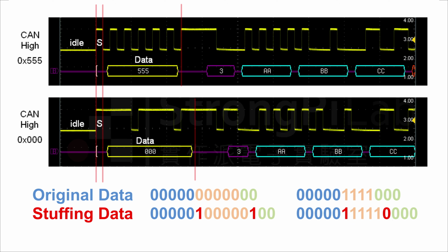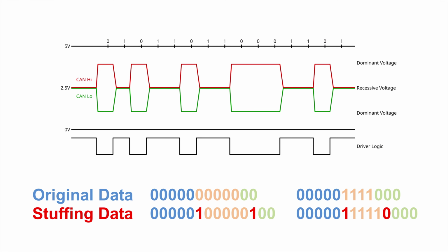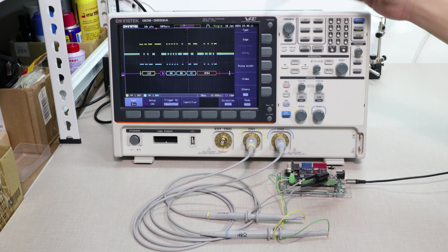Why is this so? Because, between the transmitter and receiver of the CAN bus, there is no independent clock for synchronization. They can only synchronize through data changes. Hence the data cannot remain unchanged for a long time. Otherwise, the receiver will be unable to determine if the signal is faulty, or if it is indeed a continuous signal. Thus it needs to reverse phase periodically. Thus the receiver can synchronize with the transmitter. That's essentially what CAN bus is all about.